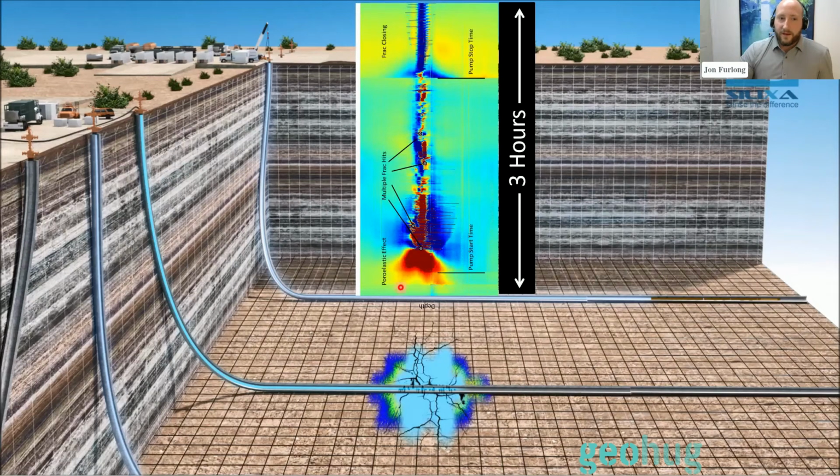In the red here, that's when the fracture tip is approaching the monitoring borehole, and you're seeing tension in the fiber. Then as the fracture tip progresses across the monitoring borehole, you're seeing tension and compression, that push and pull and squeeze on the fiber. And then eventually, when the treatment program's over and they shut down the pumps, you're seeing that relaxation. So this is just giving you an appreciation for the fidelity of the system and all the capabilities of DAS and what it can measure.